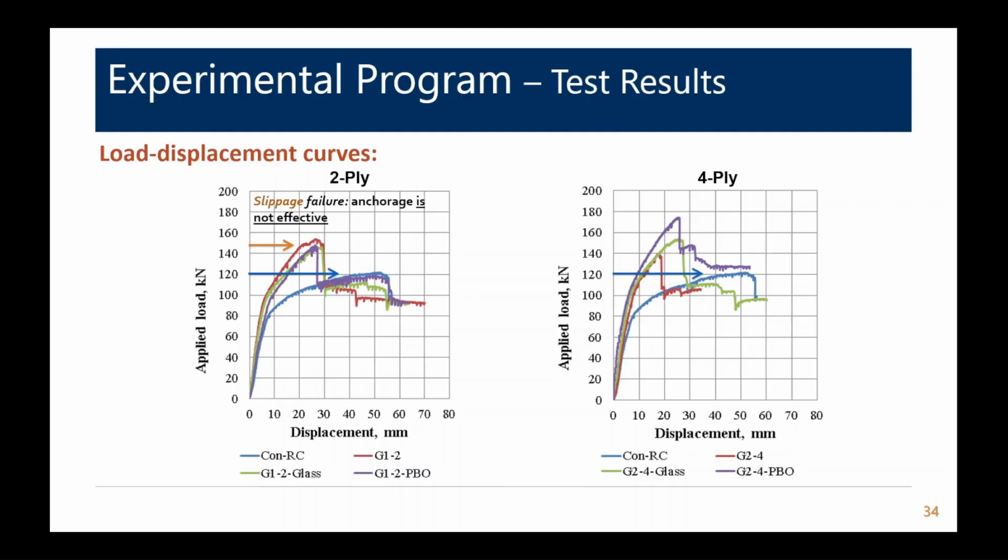However, when we shift over and we're dealing with the case of a higher reinforcement ratio where we get a debonding failure, you can go from no anchoring system in red, to the spike anchor system in green, and then the U-wrap system that we did with the PBO fabric.